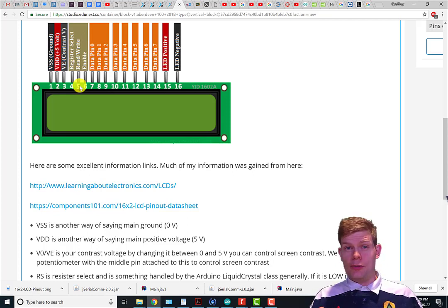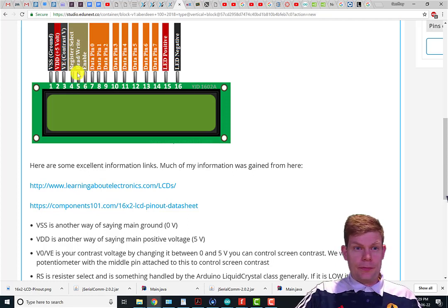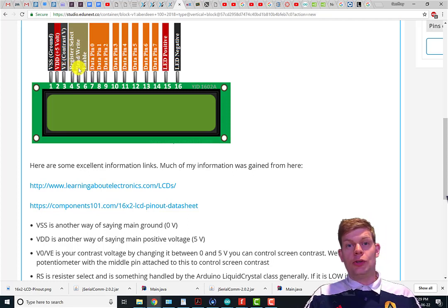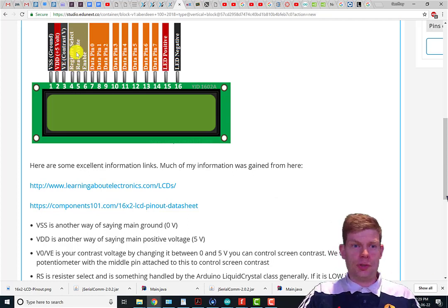because the read mode, if we had it at 5 volts, this guy right here, I put in read mode, and that would mean our Arduino would be reading the contents of the screen from the LCD through the data wires, which we don't need to do. We put that information there. We told it to draw that stuff. We don't really care after we've drawn it. But you might for some applications. So that's what that does.